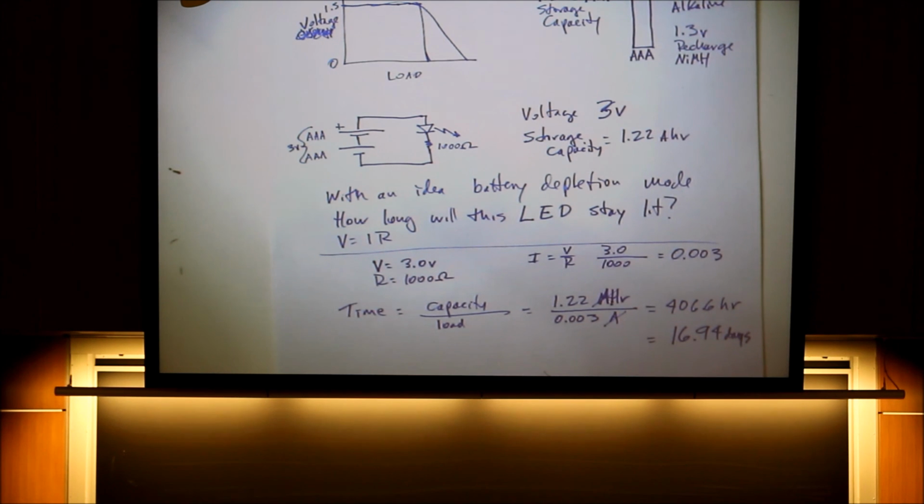All right, question over here. If you put the resistor before the LED, wouldn't it make a voltage drop before it? Correct, but it's the current that lights the LED. And hey, here's a good question for you. Can you test that out? Yes. And how can you test that out? Well, think about this. For lab number 3, you're doing an exercise where you have an LED and a resistor. Switch them up. See if it changes the light on which side you put it on.